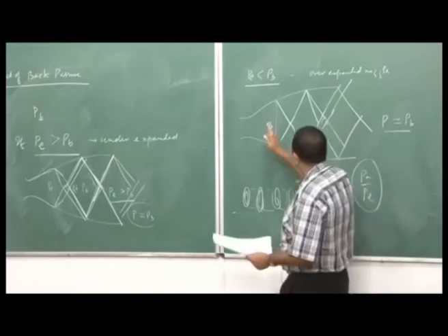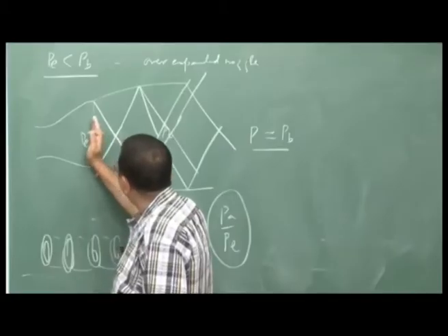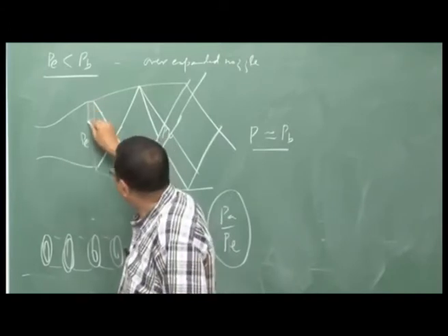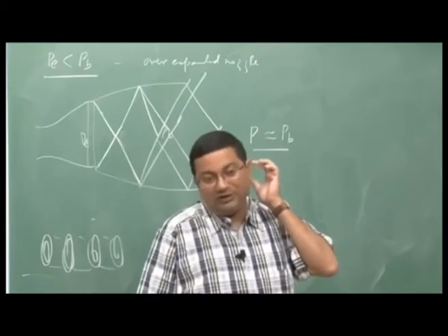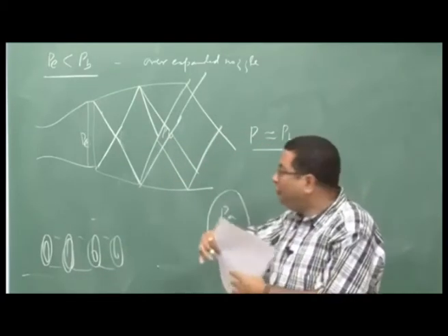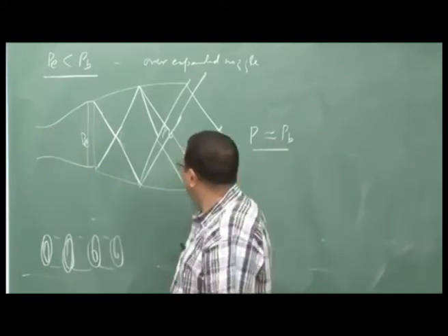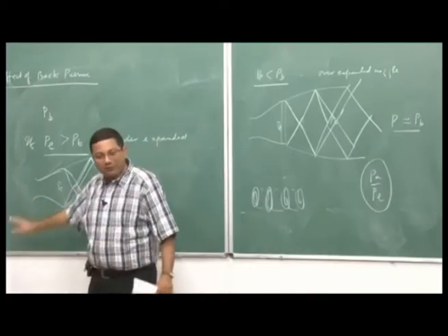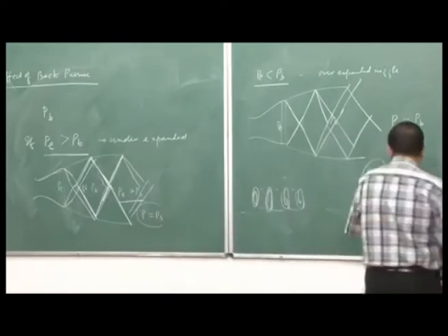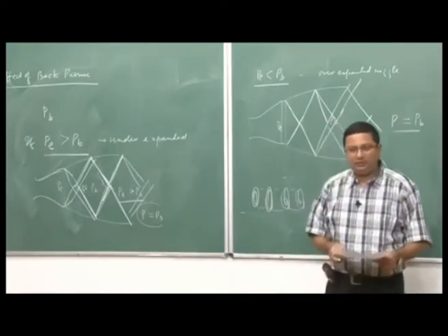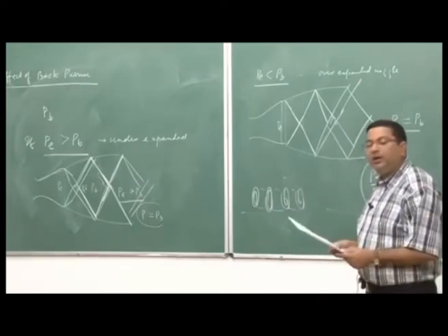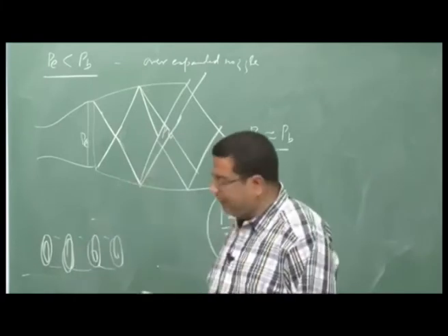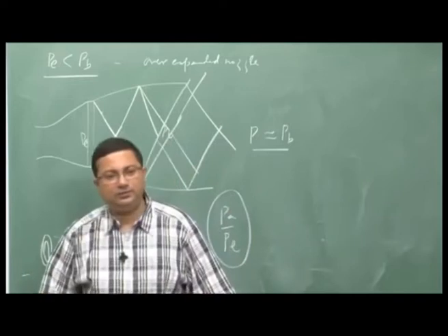Now, as we have said, if this pressure is very low, we can have a shock wave sitting here. If the pressure is even lower than this, then it will go in, right. Or in other words, if the ambient pressure is higher, the shock will go in. If the ambient pressure is lower, we will have an expansion fan here, right. So, once the shock goes in, we will have shock boundary layer interaction that we have discussed. Then there is going to be a performance drop because of the losses induced by the shock wave. All those things can greatly affect the performance of the nozzle.